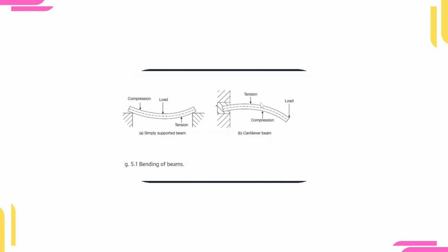But I just want you to understand that once it comes to a cantilever, the top part is the one subjected to tension, and once it comes to a simply supported beam, the bottom part is the one subjected to tension. And two, concrete is very weak in tension. That is why we always reinforce the tension zones.